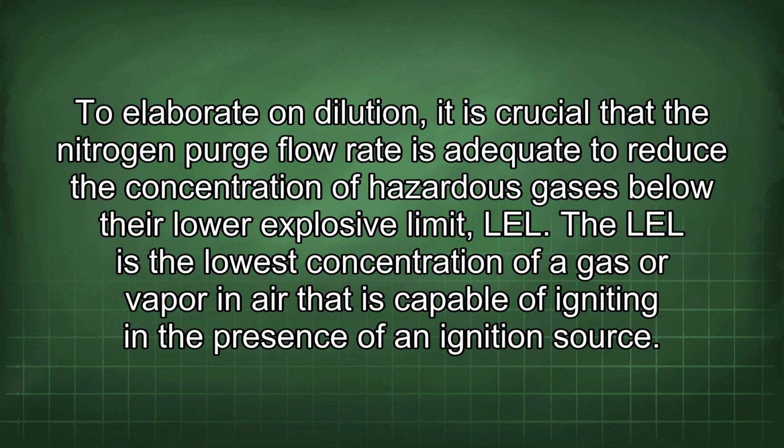To elaborate on dilution, it is crucial that the nitrogen purge flow rate is adequate to reduce the concentration of hazardous gases below their lower explosive limit (LEL). The LEL is the lowest concentration of a gas or vapor in air that is capable of igniting in the presence of an ignition source.